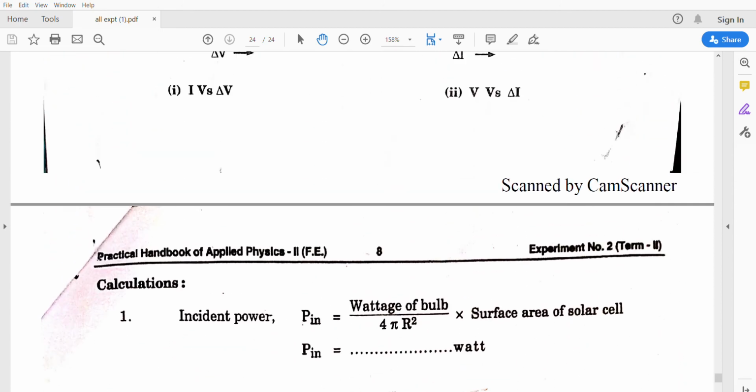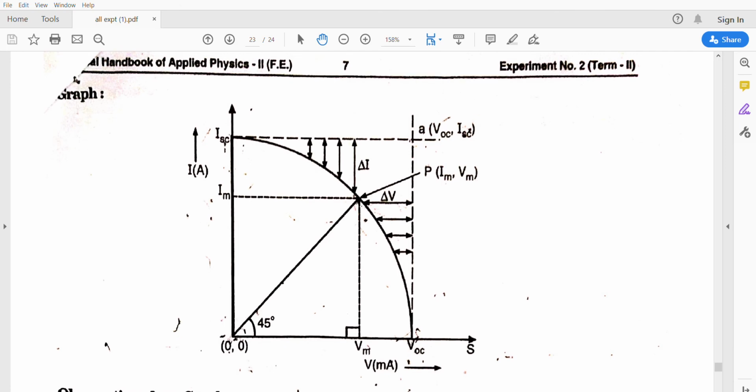When the electricity starts generating, the simple thing we have to do is change the load connected to it. First connect the maximum load, and after that slowly reduce the load, record the current and voltage readings, and draw the graph between voltage and current. If you take the voltage and current readings and draw the graph, that is said to be the VI characteristics, and it is also our aim to draw the VI characteristics.